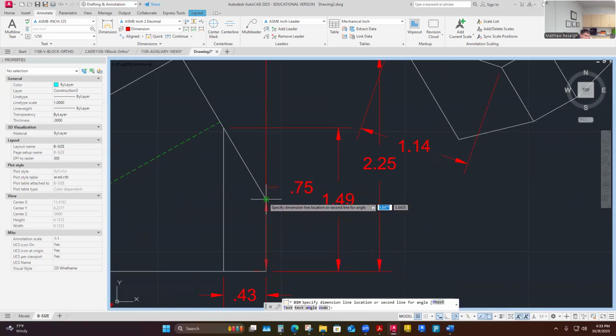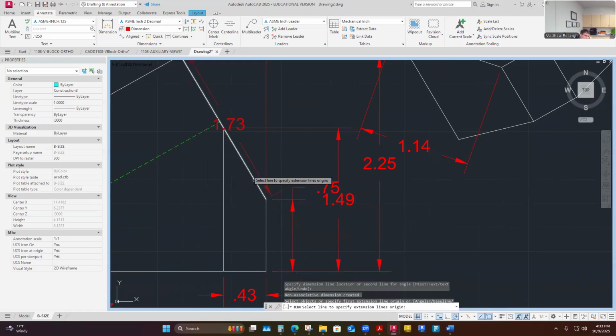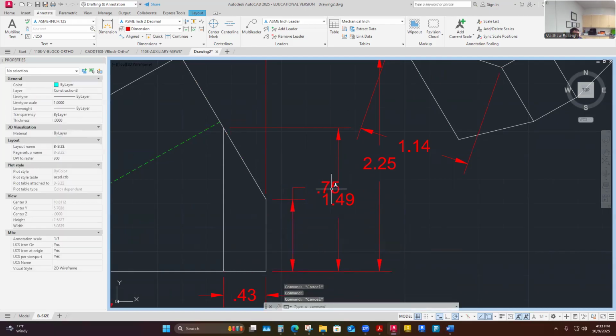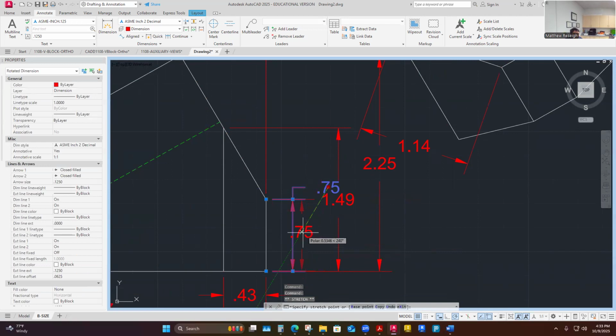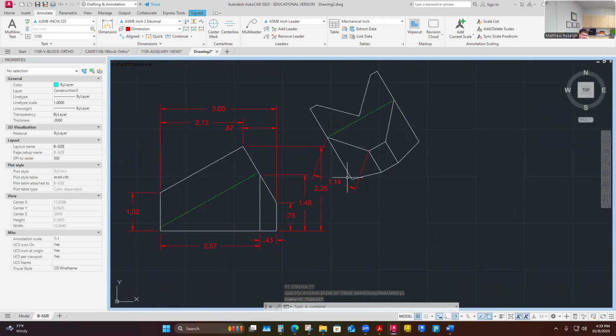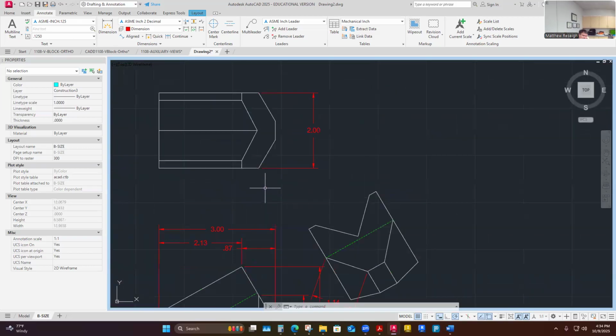But I'm really thinking about it, because I'm analyzing this surface and all the edges of the trapezoid, and then it's clashing with that a little bit. So it's definitely an intermediate dimension of those. And so then I've kind of gone there, there, and here, and now I'm going to go back this way. And where do I pick up that dimension? Well, right here it's foreshortened and going away from me. Here it is also severely foreshortened, and maybe I pick up the true dimension right here of this surface.